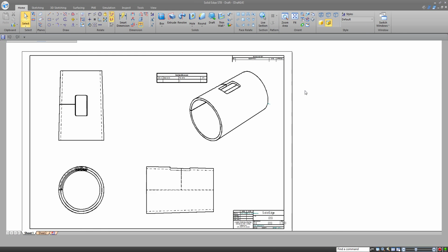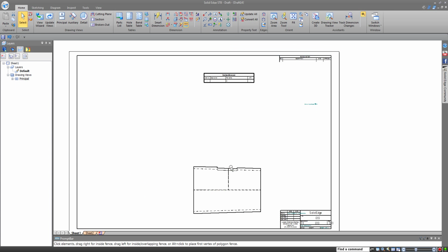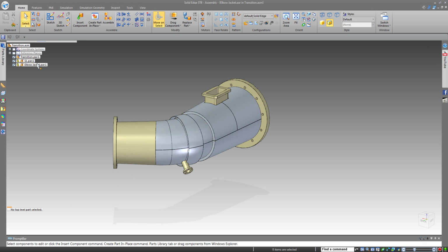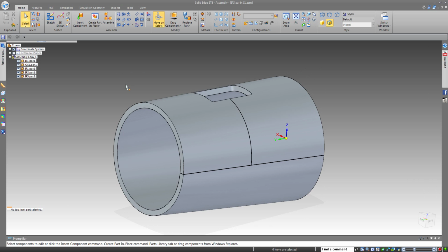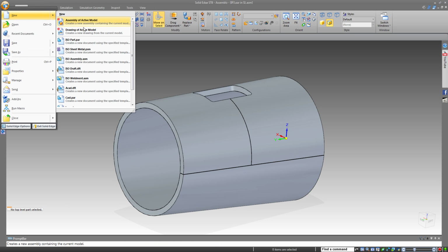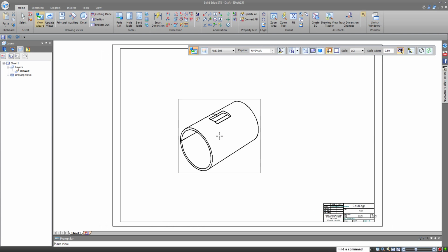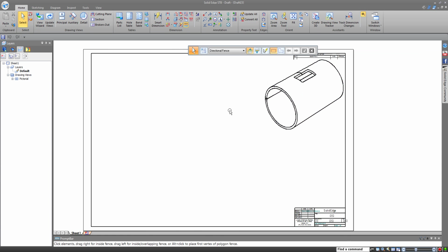Oh, sorry. Let me get out of there. I grabbed the part file. I didn't grab the right one. Here's the one I wanted. That was my mistake. That's why you publish it. Otherwise, you get a single list item in the bill of material like I just did. So here I'll get an actual correct bill of material based on the components. User error. We'll just ISO view and do the parts list again.